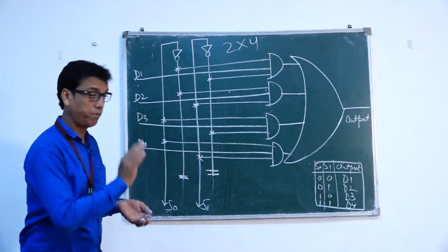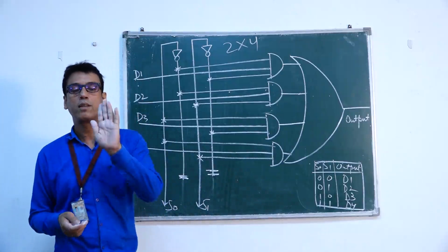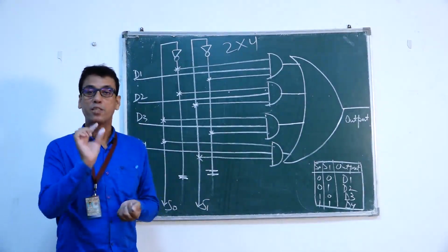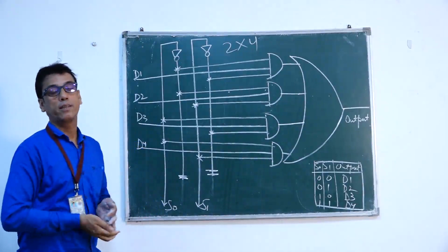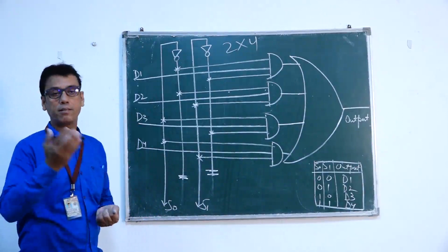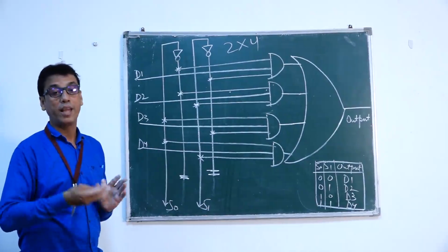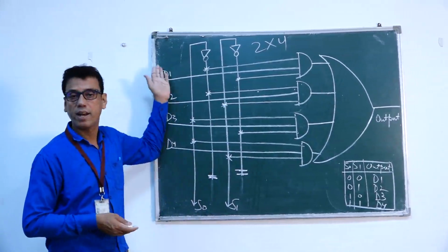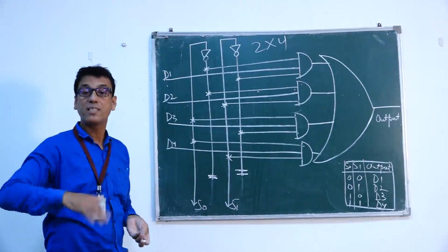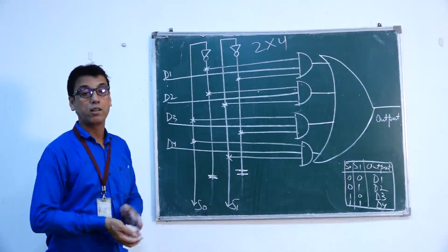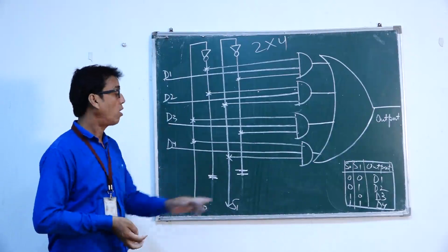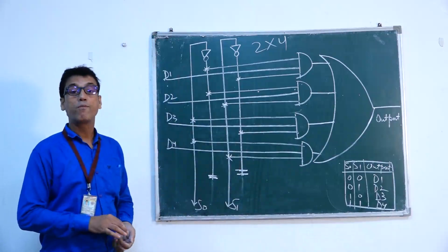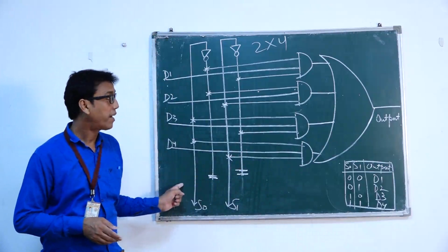Now, the first step to learn the circuit is we need to explore the main points about the circuit, the type of circuit. The multiplexer is combinational circuit. Then how many output lines it has? Only one. How many input line it has? Selector lines and device connection lines. Then what is the purpose of this circuit? Then draw the block diagram. Then draw the truth table. Then draw the circuit diagram. And finally, make a dry run.